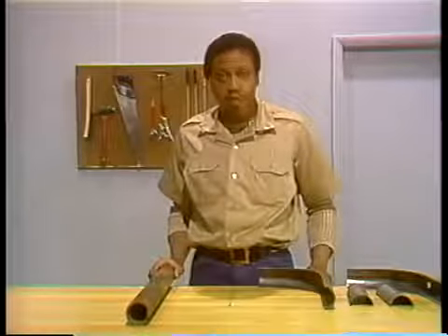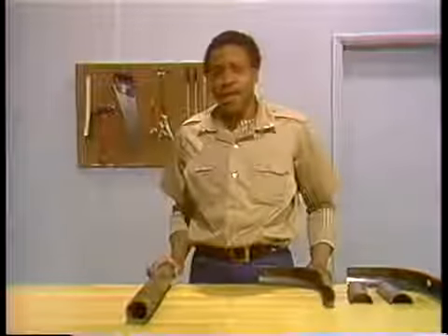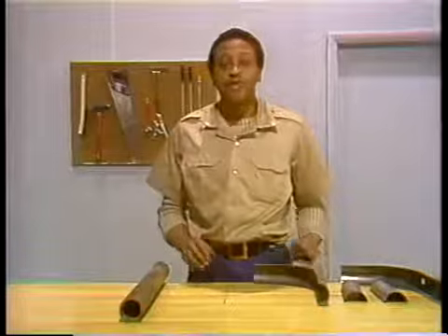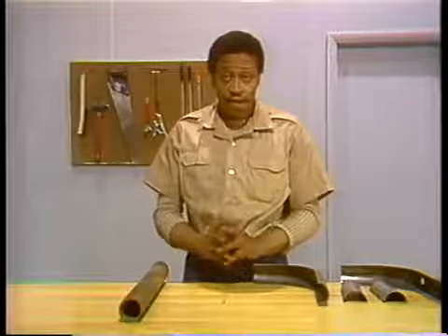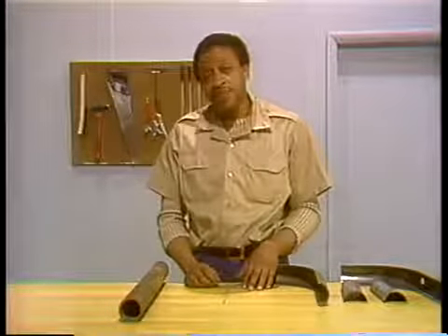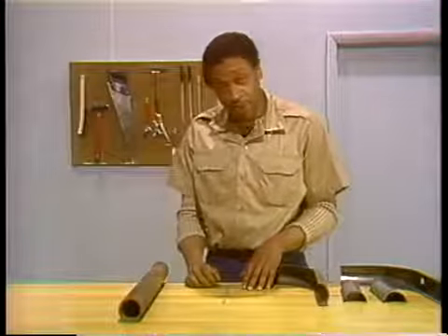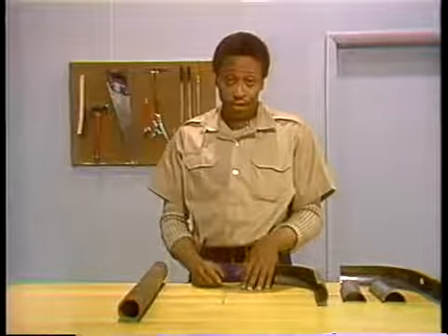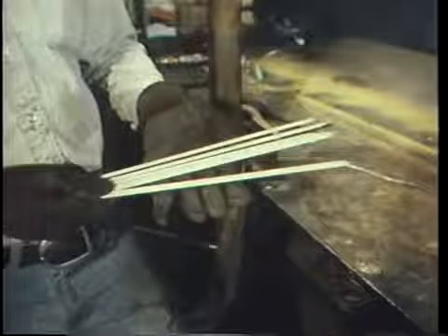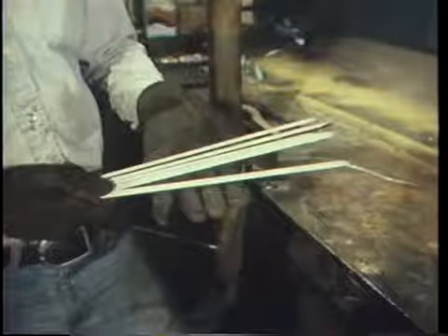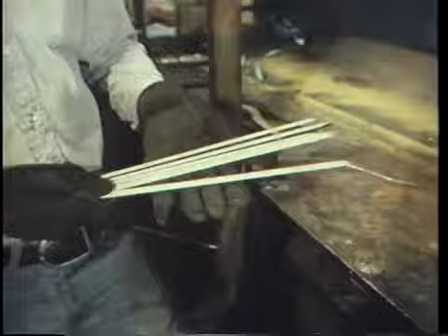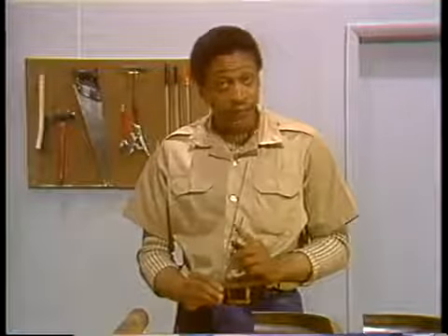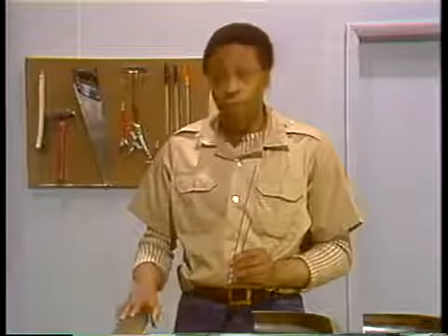Once it's been determined that a tube needs cladding, the first thing to do is to read through the cladding procedure. If a written procedure doesn't exist, talk the process over with an experienced welder. Now, the next thing to do is to get the materials and tools together. The only material that is needed for a clad repair is weld rod. It's very important that the right weld rod is used. The rod metal must be compatible with the tube metal. If it isn't, the clad patch could eventually damage the tube.